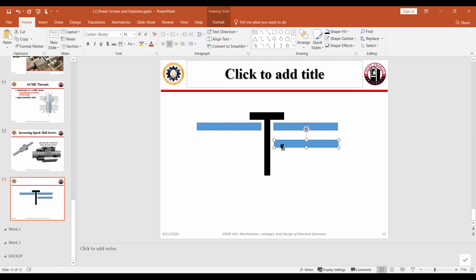And then in the second part, I'm going to want to screw it in. I'm actually going to want to fasten it to that member so that they hit this guy, which is continuous. I just drew it as 2 separate pieces to illustrate the hole. It is clamped between the member I'm screwing into, or the nut that I'm screwing into, and the head of the bolt. Right. So all these things clamp together.